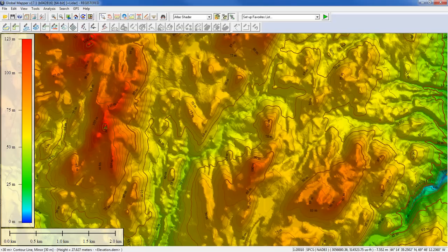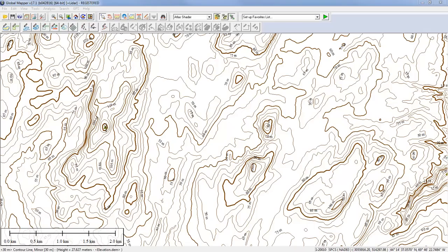In this case, I'll turn off my underlying elevation layer, and you'll see my contours have been generated very quickly, very easily. Somewhere in here there should be a couple of spot heights. I can see the max elevation right here, this little green triangle. Not quite sure where the min is. I think it's off the side of my screen over here on the right side. But again, most people would be concerned with determining the high point. Perhaps if you're initiating a viewshed analysis, you want to determine the high point within an area. That's a useful byproduct for that process.